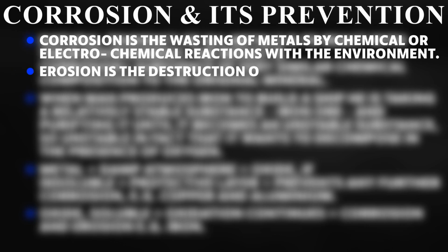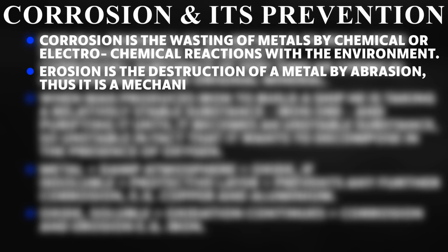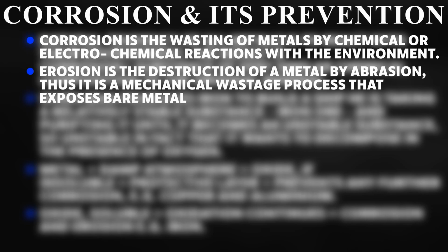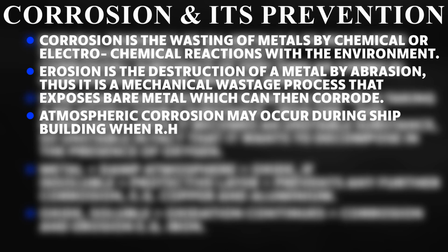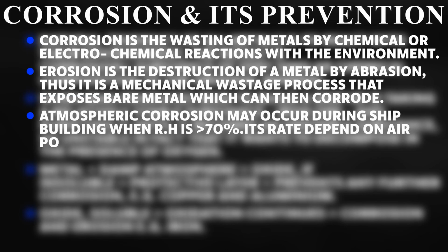Erosion is the destruction of a metal by abrasion, thus it is a mechanical wastage process that exposes bare metal which can then corrode. Atmospheric corrosion may occur during shipbuilding when relative humidity is greater than 70%. Its rate depends on air pollution by smoke and/or salt.